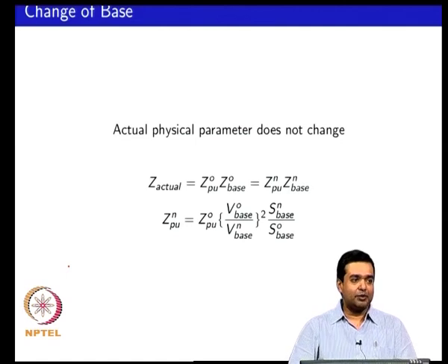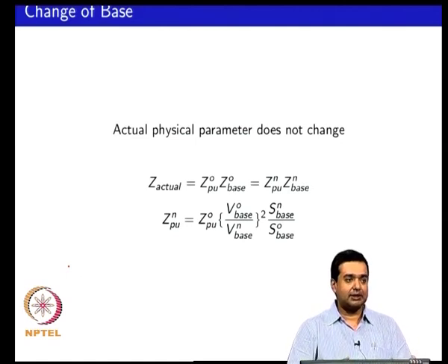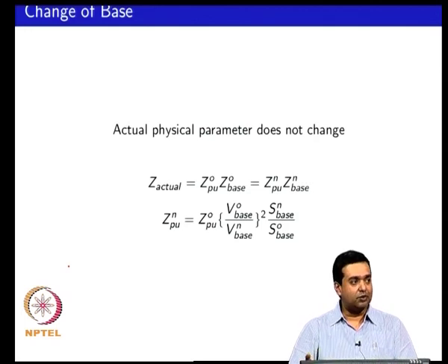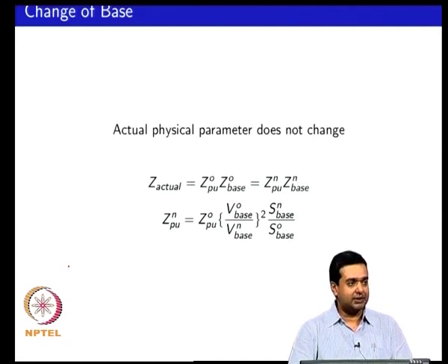One is that per unit means it does not have dimension, while 230 volts is in volts. So, you are writing a quantity equation where the dimensions do not match, and one is not 230. It would be okay to say 1 per unit corresponds to 230 volts, or the base value is 230 volts. So, be careful when you talk about quantities on a per unitized basis.